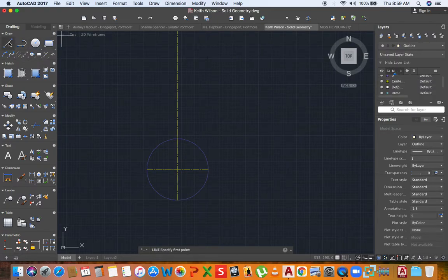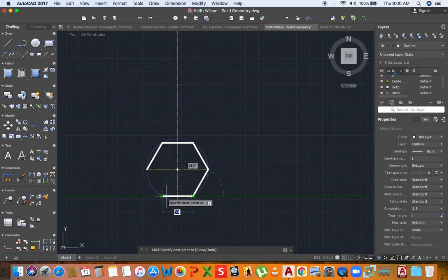I'm changing up the method a bit, and I'm going to ensure that I've selected 30 degrees here. Once I've done this, I'm going to at this point go up, ensure that it's up 60 degrees. Then I'm going to go across, then go down to this point, 60 degrees again. Well, sometimes you'll see 120 or increments of 60. Doesn't matter. So I'll draw my hexagon.